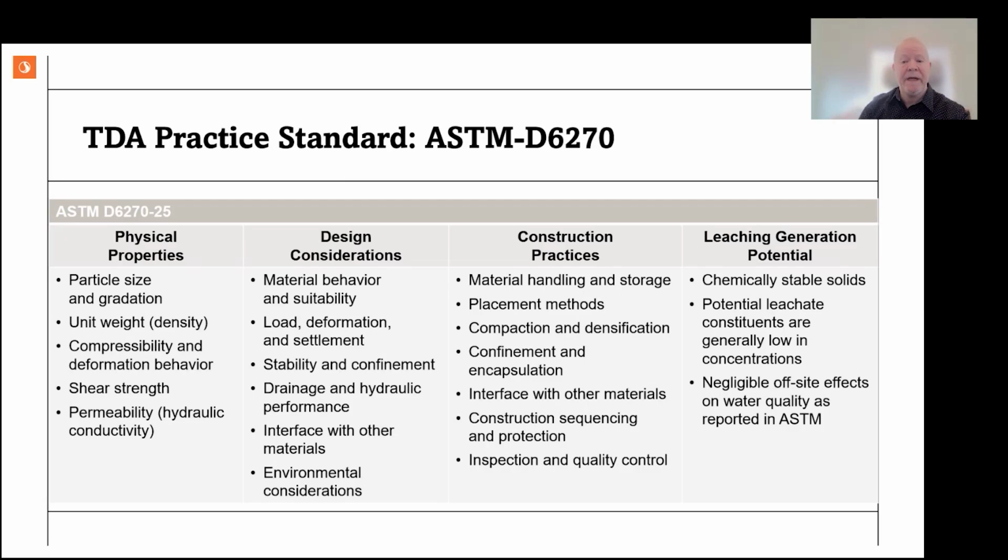The standard explains how to evaluate TDA's engineering properties using adapted geotechnical testing methods. It also emphasizes that TDA behaves differently from mineral aggregate, so testing and design approaches must account for that. It also outlines practical construction guidance: handling, placement, confinement, inspection, and finally, quality control.